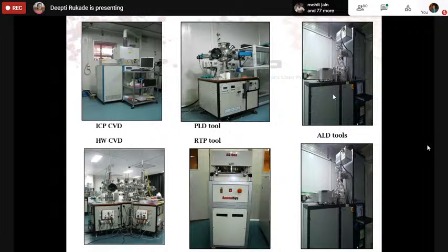Now this tool is mostly used after implantation. Okay, so that is one use. Then the second use is, suppose I have a silicon wafer. I need to grow a very thin oxide for some tunnel oxide application, or I need a very thin layer of around a few nanometers, say 5 to 12 nanometers.